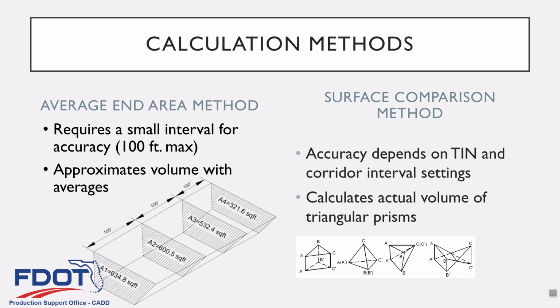You change the stroking definition, which we did in chapter 4, will affect that. And the other thing with the interval settings, if you have that densify curve option, it'll make it slightly tighter when you get on a curve, even on the main line of a corridor, which also helps to become a little more accurate on the curves.